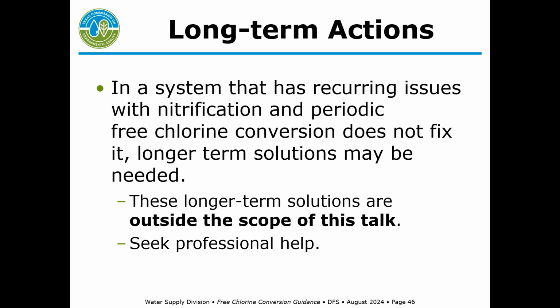So what if the free chlorine conversion is not enough to fix the problems? You have these recurring issues with nitrification, and the free chlorine conversion doesn't fix it. You may need some longer-term solutions, and those are really outside of the scope of this talk. So I recommend you get some professional help with that.